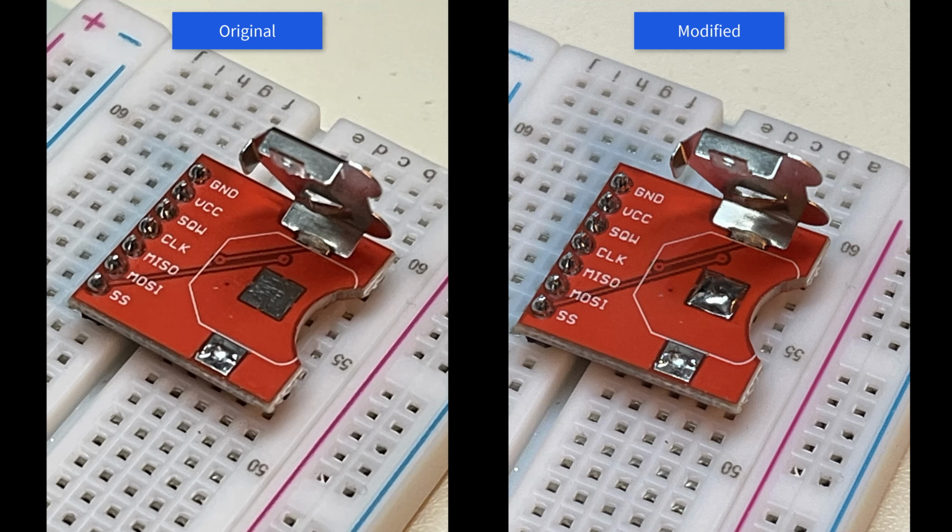Well, I pulled up the top. This is kind of the outer shield, which is the positive side of the battery. I pulled that up and was looking at this pad, and the pad is just kind of a poor design. The pad is actually recessed a little bit. It doesn't stick up, and there's just no way the coin cell was going to make contact with that. So I just soldered a bump on top of that, soldered the outer plus positive shield back down, slid a coin cell back in, and now everything is working great. So it was just a poor connection of getting my actual battery power to the IC for the real-time clock. Quick little fix, and all is well.